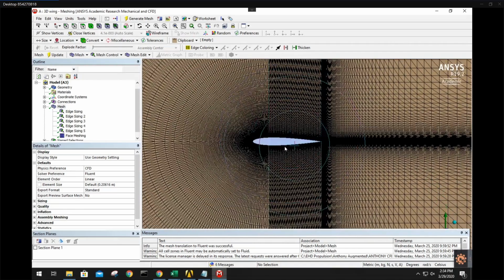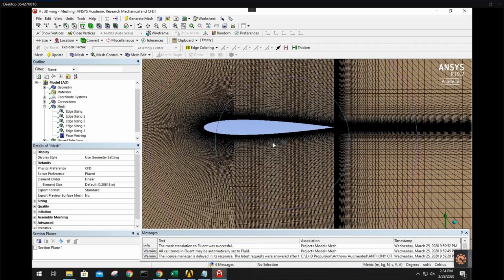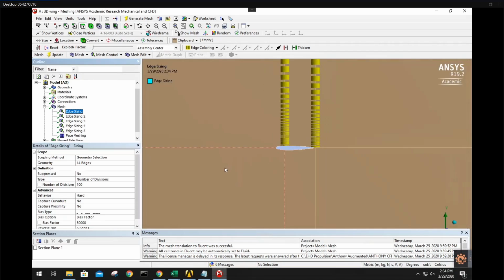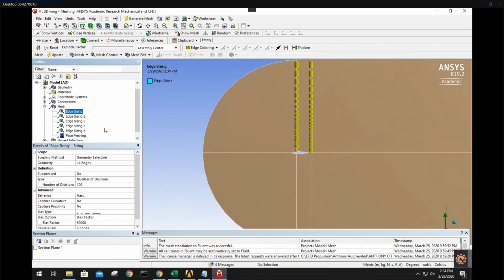So today I want to show a different way to mesh and run a 3D simulation that uses wall functions or the K-Epsilon model. It's a great way that reduces computational demand. And it is much simpler, something that doesn't take time to learn how to do these 3D edge sizings, because this took me time to think about. And you don't really need to think about the topology because we're going to be using inflation layers.